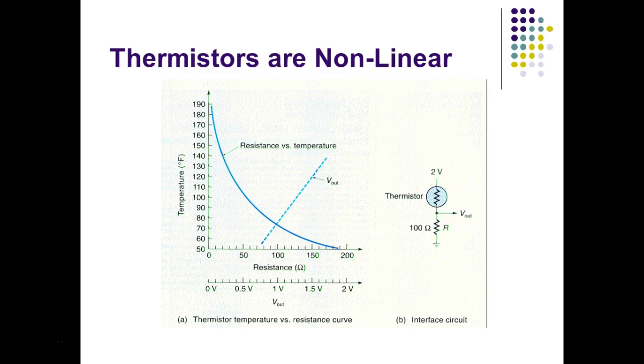You understand that? But if I swap them around, then I'll get a voltage that goes down with changing temperature. Here we get a voltage that goes up with changing temperature just by the relationship of the 2 resistors. But the problem is I have no reference for that voltage. That voltage right now means nothing. All I know is that the temperature goes up, right? You understand? Now the voltage goes up. If the temperature goes down, the voltage goes down.